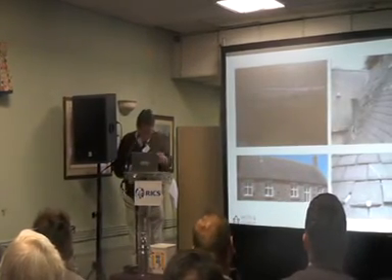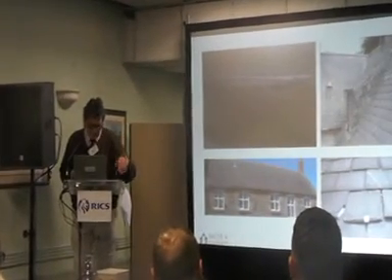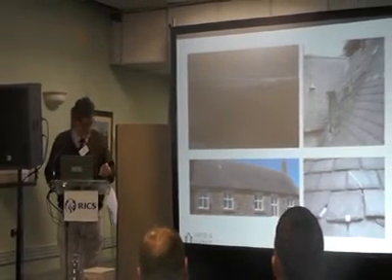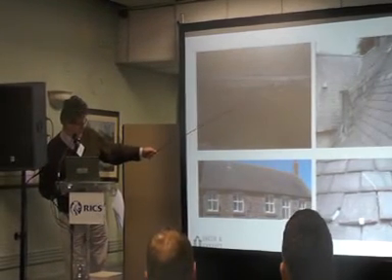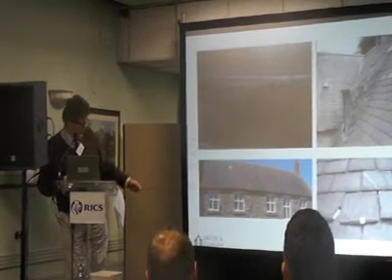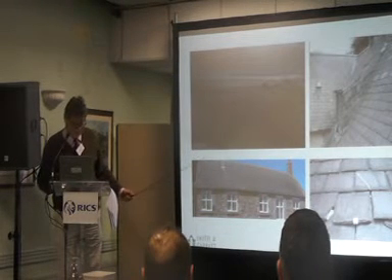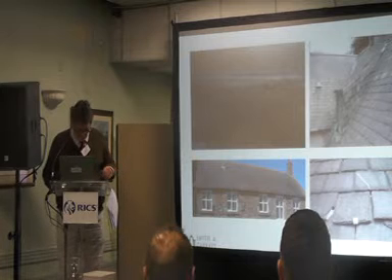So on with roofs while you're doing that. Top left, I'm looking down the inside of a sarked roof, and you can see the ends of the nails. So when you're doing a survey, look for that. That is an iron cut nail, square in section. Obviously, you can see where a roof's been repaired using either copper, galvanized, or whatever. That's the place to look to see what you've got.